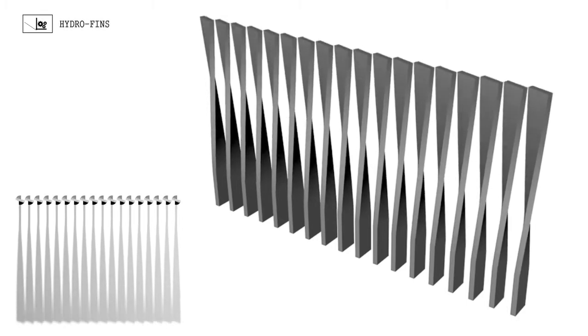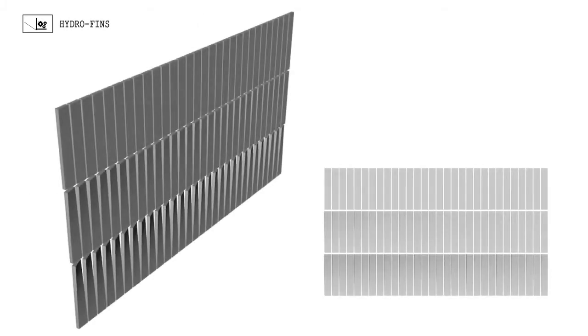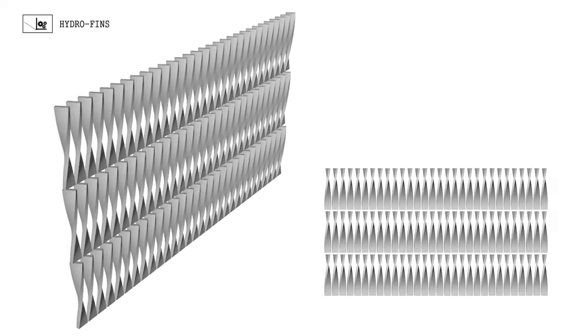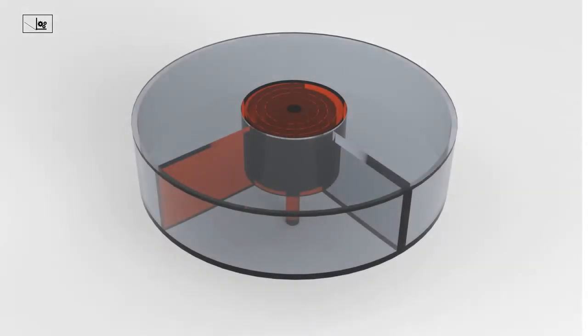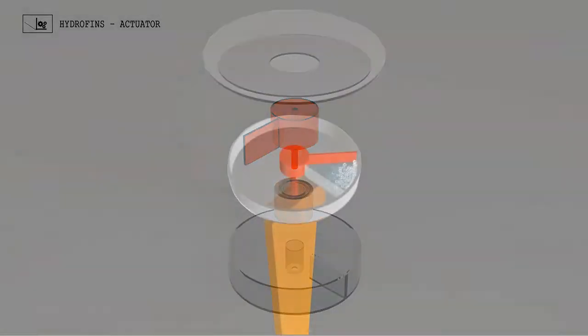Hydrofins is a component which uses mechanical properties of hydrogel to actuate fins. Hydrogel balls are used to push the pivoted arm of the component, which enables rotation of the fins, rendering them open. This component consists of a chamber for hydrogel, catchment for rainwater, and a torsion spring to push back the arm to its initial state once the balls deswell.